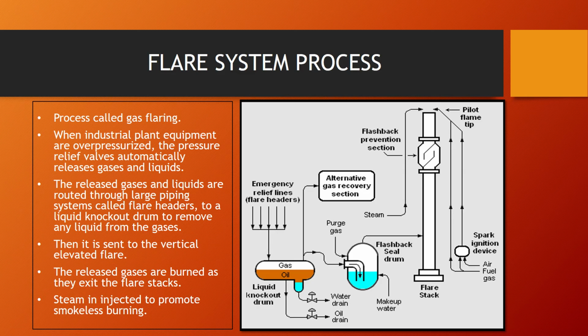Then it is sent to the vertical elevated flare and the gases are burned as they exit the flare stacks. Steam is injected to promote smokeless burning.